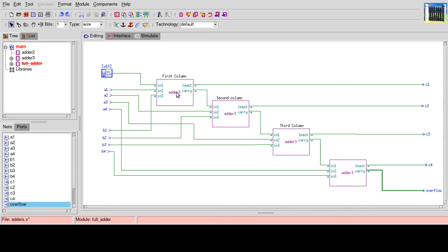And so you can see here that basically you've got 3-bit adder, 3-bit adder, 3-bit adder, and what's cascading between them is the carry. So the carry from the previous column is fed into the next column, and that's exactly how you add. Basically, I just looked at how I added my binary numbers, how I did long addition. I had a machine to do 3-bit addition, so I said, well, every column is 3-bit addition, so every column has to have a 3-bit adder. And then I said, I take the carry from the previous column and feed it into the next column, and the least significant figure I just write below the line. So I just built a machine that does exactly what I do with my mind. And there you go, there's a mechanical mind, designed.